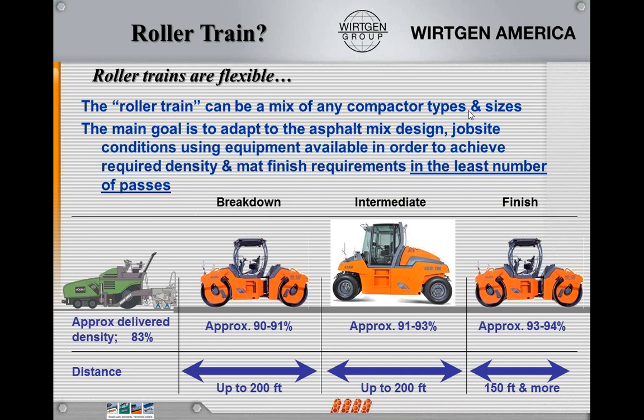Now, the other thing about a rubber tire roller, it should never stop. That rubber tire roller should constantly be moving. You're not going to destroy a mix with a rubber tire roller. If it gets into a tender zone, we might need to back off a little bit if it gets too tender, but we definitely are not going to destroy a mix with a rubber tire roller. It should never stop. A lot of people have a tendency to stop on the mat, and they say, well, the tires will stay warm.